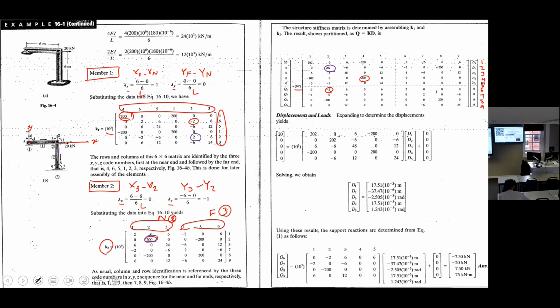And you need to comply with the boundary condition, which means that you need to go to your structure to see which supports you have. I have a support in node 3, which means that the deformation at degrees of freedom 7, 8, 9 are 0. And also a roller support at node number 1, which means the deformation along 6 is 0. Right? So 6, 5, 7, 8, 9. 4 degrees of freedom have deformation equal to 0.